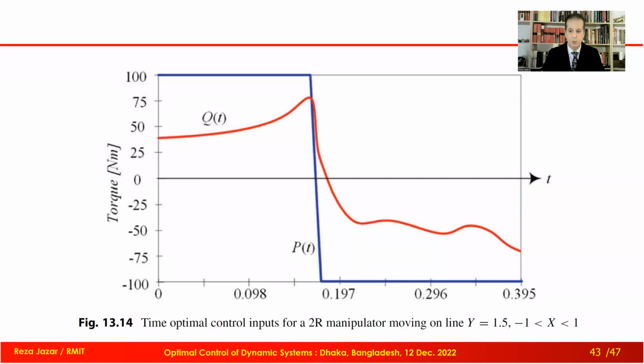As you can see, this solution with that numerical value says that the motor on the ground must be saturated from the beginning up to some point, where it switches to the minimum to stop the robot at the end. The motor on air has some value within the limit at any time. That's the solution. Now we find the switching point.